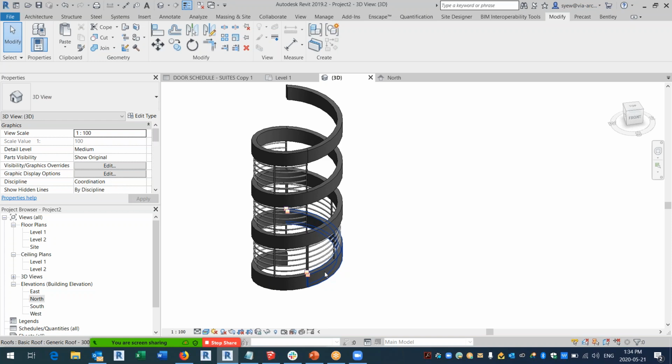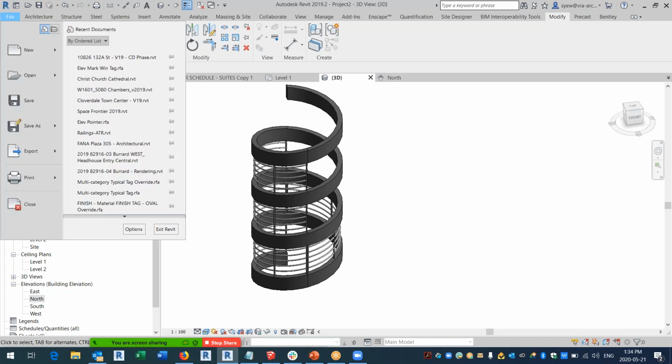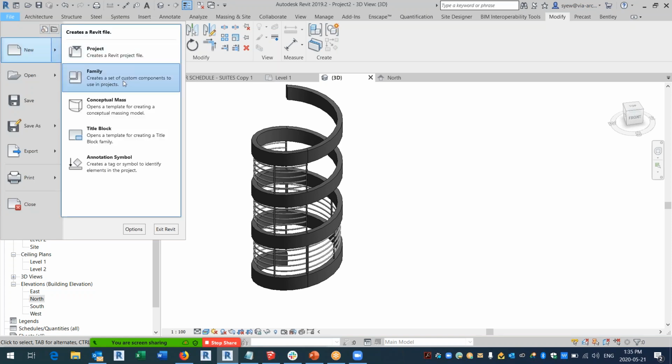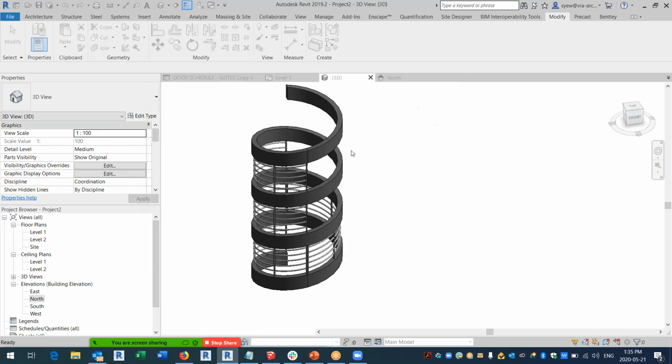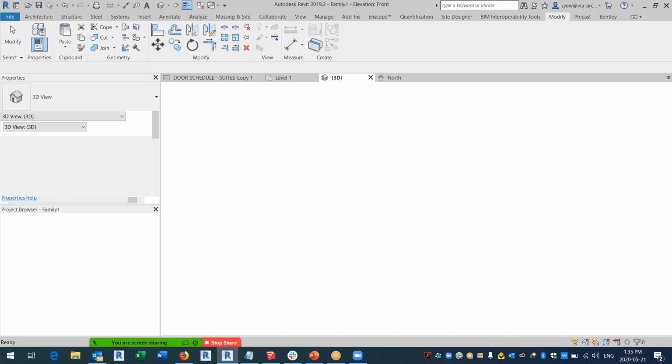Okay, the next thing I'm going to talk about is how you build a scalable family. I did this in the past. I just want to repeat it again. The reason is that you sometimes need something to scale, and Revit is just becoming such a pain. So the first thing you want to do is that out of all the families, the only families that can actually scale things would be your trees. So you kind of have to use planting as your first template.